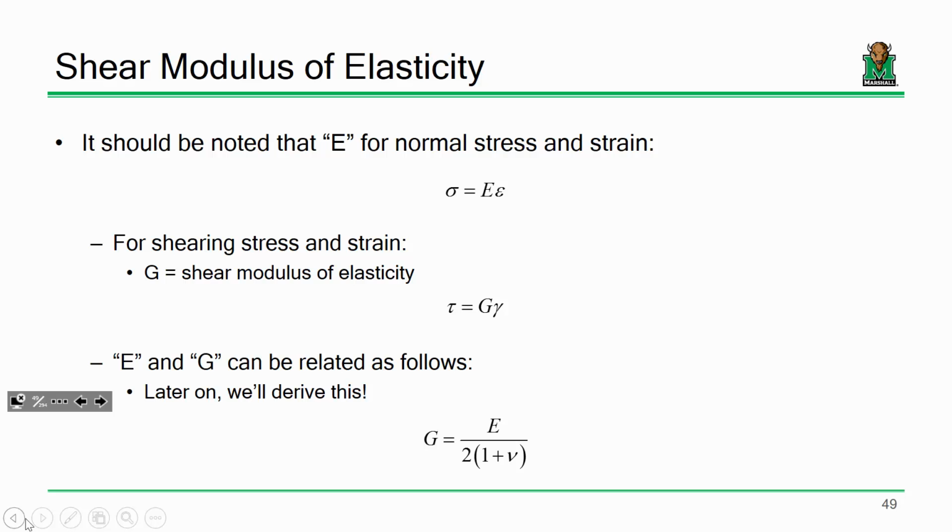All right. We will talk about this in greater detail later, but what we have been talking about so far is axial load and axial stress. Take a member and yank on it. It generates an axial stress and an axial strain. They are related, okay? Similarly, if I take a value and I shear it, I get a shearing stress and a shearing strain. They are related. We call that the shear modulus, G. Now, you can derive G pretty easily if you've got E and you've got Poisson's ratio by just plugging and chugging. Later on, we'll talk about how we would derive this, okay? It takes a little bit of time to get there, but for now, just believe me, we will derive it, I promise.